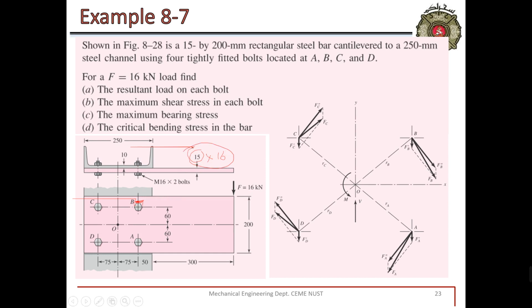This is equal to the bearing stress of the bolt or the bearing stress of the plate, both cases. Similarly, for this plate as well, we have bearing stress, and the area is 10 times 16. Force divided by this area gives us the bearing stress in this plate as well.